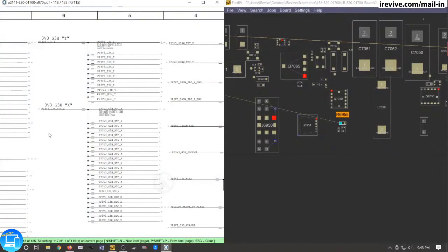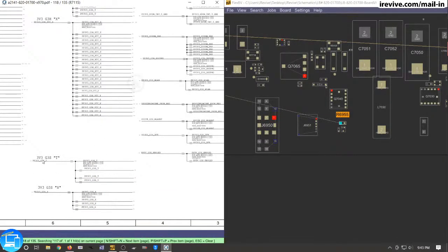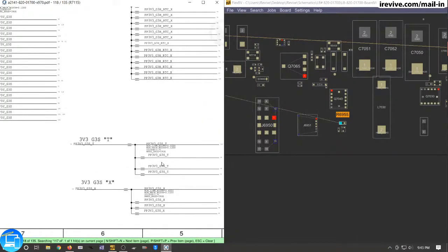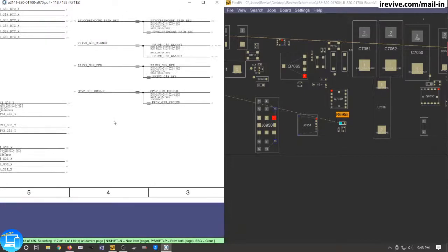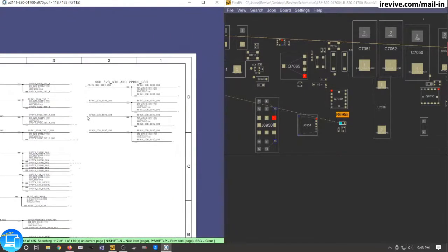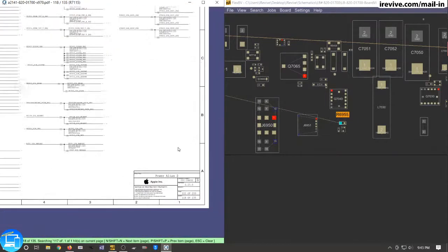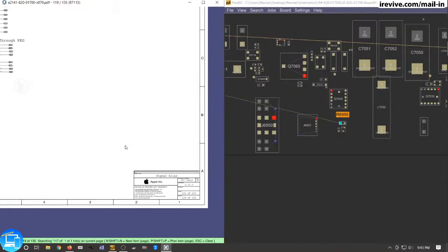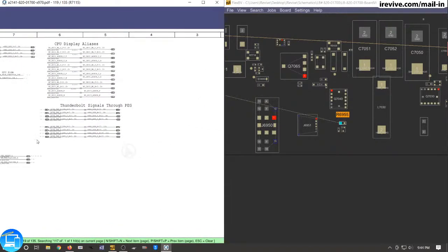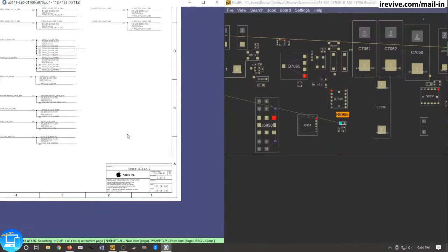Okay, so we know that our PP3V3 G3 hot is present. So these look like these are all G3 hot or G3S. I don't know if that is G3 sleep, standby. I'm not sure what the S stands for in this regard. So is there any other power aliases that I might be overlooking here? Let's see what's on our next page. Next page is signal aliases. This isn't going to be anything we're looking for at this particular moment.